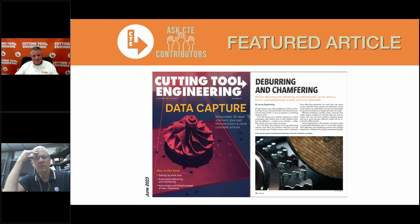Well, I think one of the tools that I've seen is a chamfering tool. I think this is what you're talking about, that you go into the hole for cross drilling, you go into the hole with a dead spindle, and then when you turn the spindle on, an actual insert through centrifugal motion opens up as it's spinning and allows you to back chamfer a part, back chamfer an ID, so to speak.